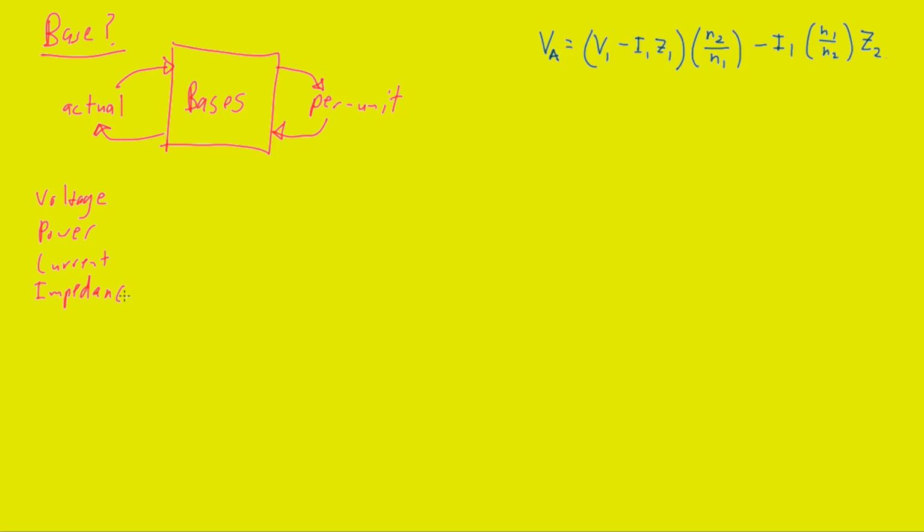Now, as far as the per unit method is concerned, no base is really more important than any other, but we'll see very clearly that the bases voltage and power are really the preeminent ones in the use of the per unit method, especially as we see it for PE style questions. Voltage and power are going to hold the dominant role. But realize that's not because of the method, it's just because of the practice.